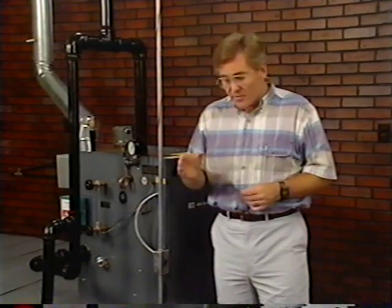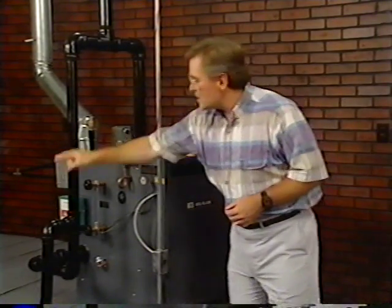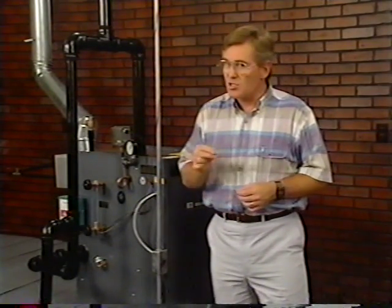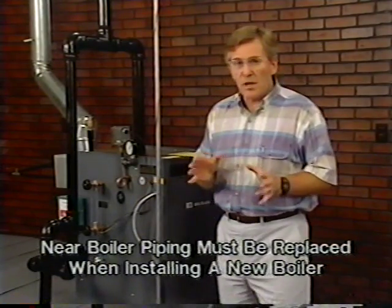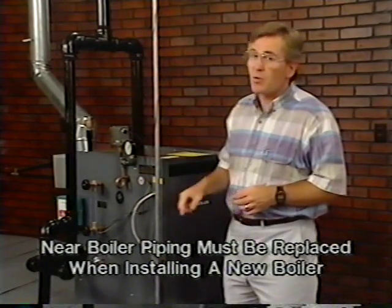We now know how a steam boiler operates, some of its components, and how it heats a home. Let's look at the piping around the boiler known as near boiler piping. This piping should always be considered part of the boiler unit, since it is critical to assure proper steaming. Therefore, if you replace a steam boiler, the near boiler piping must be replaced as well.